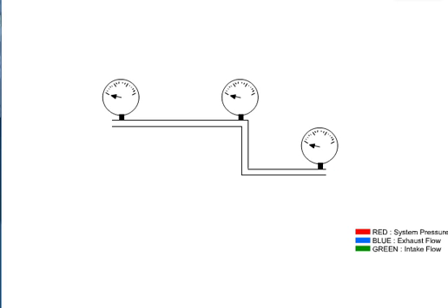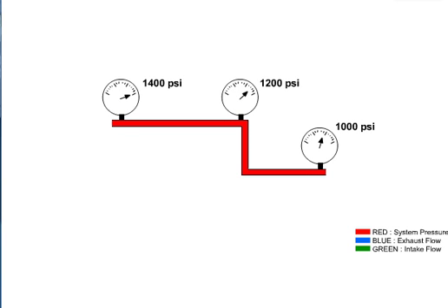This resistance to flow is load-induced from the actuator and also generated as the fluid is passed through the various conductors and components. All points of resistance, such as long runs of pipe, elbows, and various components, are cumulative in series and contribute to total system pressure.